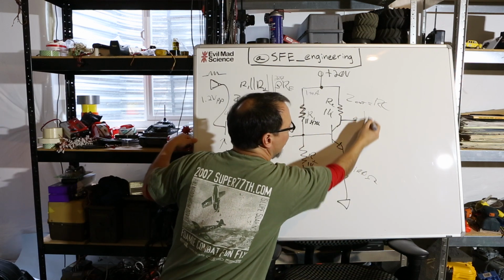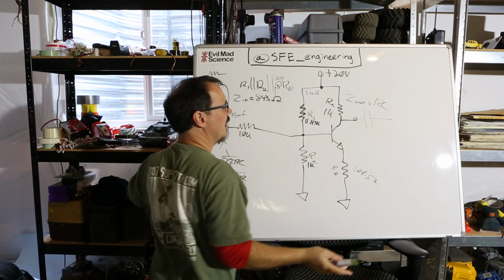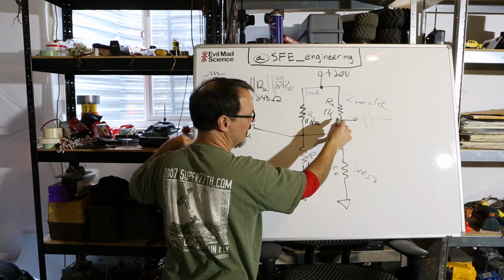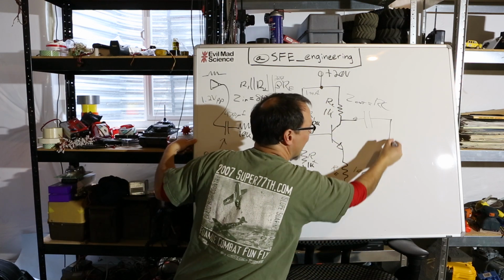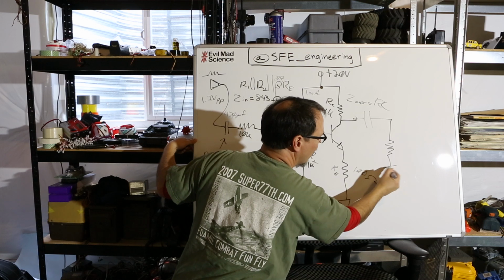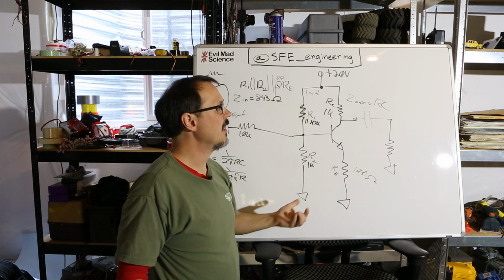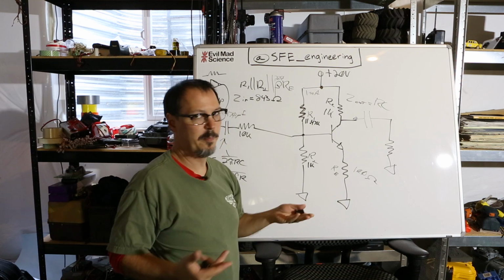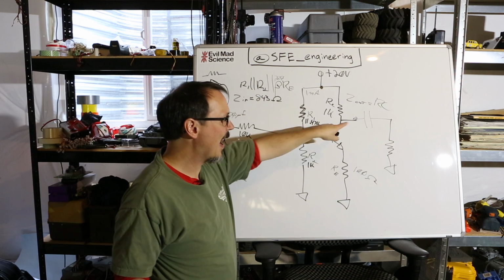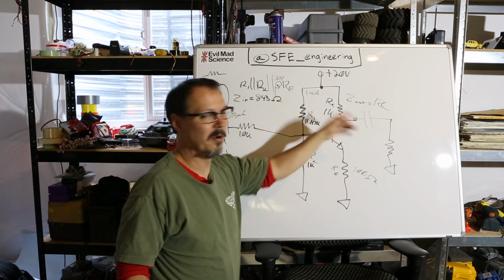You're going to calculate a value of cap based on the output impedance of your amplifier and whatever impedance your load is going to be. Same thing as with the input. You want to calculate that thing so that its capacitance value is big enough that it is not impacting the equation of where the voltage is going.